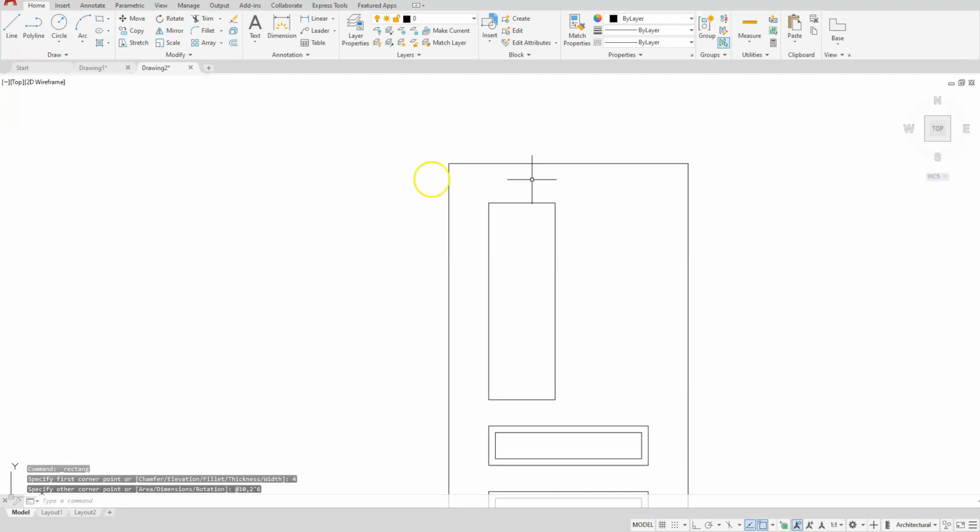Now you'll notice at the top of this it has a radius on it. And it doesn't give you the dimension of that radius, but you know the width of this. So if I know how wide this is, which is 10, the radius of that should be half of that because this is nothing more than the diameter that goes across. So that radius is at 5. So let's go to fillet, radius, 5, enter.